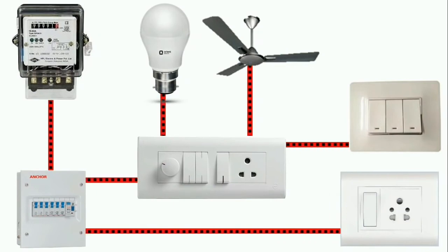So this is basically a basic introduction, just to give you an idea of what to choose when it comes to your cabling in your installation. Because the more quality the materials you use, the more reliable and the more efficient these appliances would work and function well. So from the meter to a distribution board, it's recommended that you use around 4 to 6 mm, 4 to 6 mm square, from the meter to the distribution board.